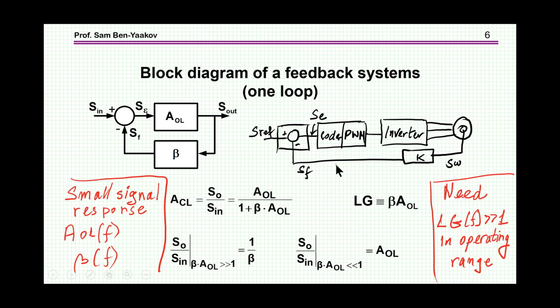Only the K or the beta here. Now, you are in control of this K, beta, make it whatever you want. So this means that you in fact can control the output independent of the characteristic of the motor in this case and the inverter, just by designing correctly the controller and of course the beta. This because the relationship depends on beta.